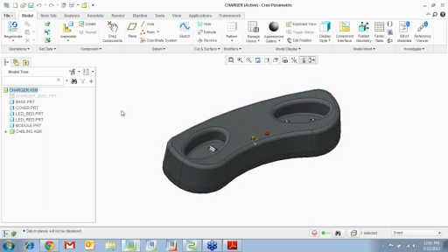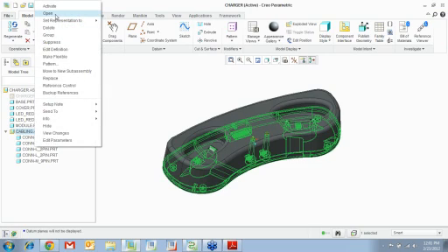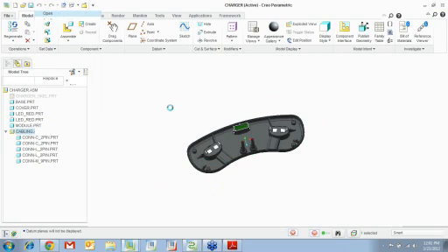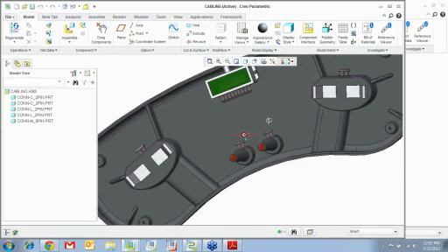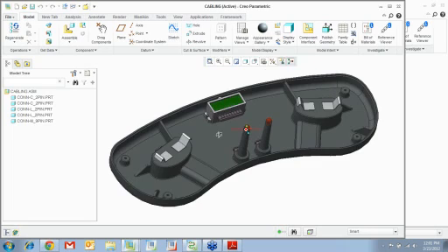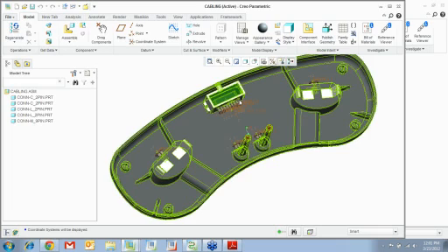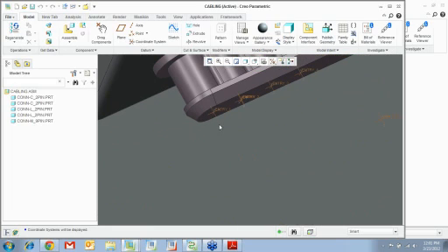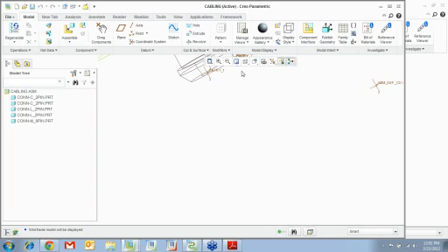So I have a charger assembly, I have a cabling assembly within that. I'm going to open this little cabling assembly and you can see I have some components right here, electrical components, and I'm trying to route my wires to them. Now what's also important to note is that all these components have coordinate systems with certain names. See that entry 1, entry 2, entry 3, so on and so forth. And I want you to also observe that the Z direction of that particular coordinate system is pointing outwards. I apologize if you cannot see it very clearly, but you can see the Z is pointing outwards.